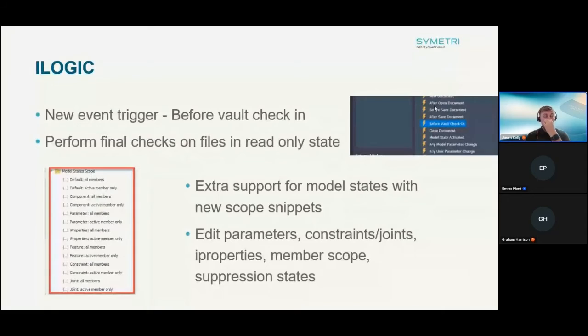So the new event trigger they've added is mainly for the Vault users because it's before Vault check-in. Now, what's great about this is that if you're wanting to keep your Vault standardized and clean, you can make sure that when you're adding in these particular properties, or you're wanting to make sure people are adding in the properties, that it won't check it in. So it's going to perform any final checks, and it will perform it in a read-only state.